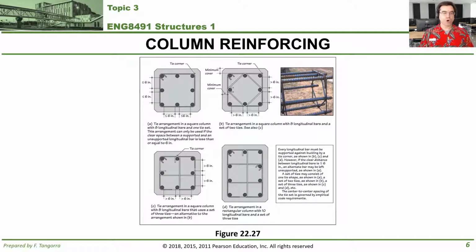Concrete reinforcing can be set out in very different ways, but for the most part it follows the same pattern. You can see here, this is a section cut out, a slice cut out of the concrete column. You have a tie with rebar, longitudinal rebar placed at the corners and halfway between the corner rebars. This is the kind of setup that you'll see typically if the rebar is spaced no more apart than 6 inches. So that's about 150 millimeters.